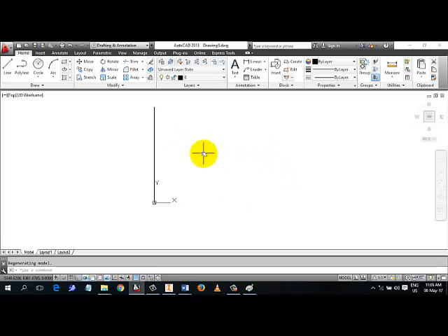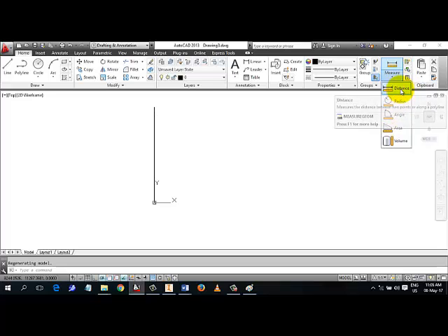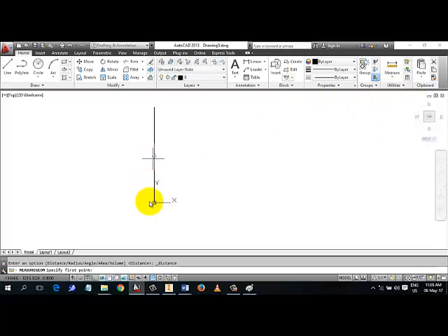Okay, I have my line in place now. The length of this line, if you are not sure, all you need to do is to go to menu. You are doubting. Click on distance. Click the beginning. Click the end. What does AutoCAD tell us there? At the information section of the command window. Command window is broken into two. We have the white section, we have the gray section. The white section is where you type your active command. The gray section will give you extra information.